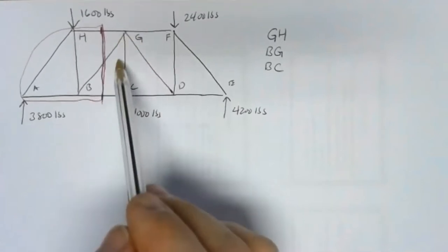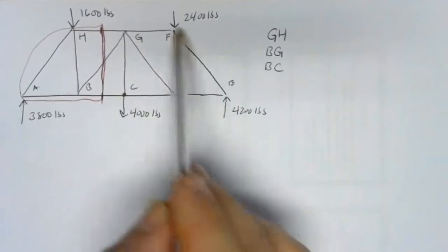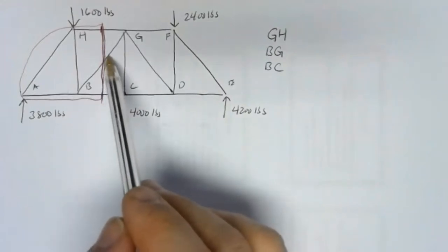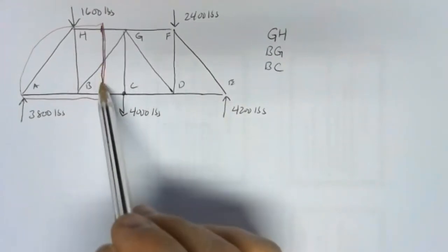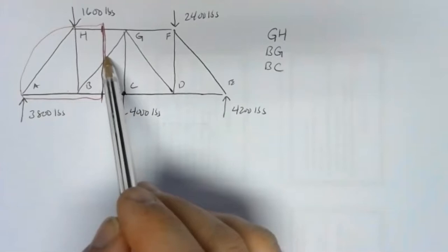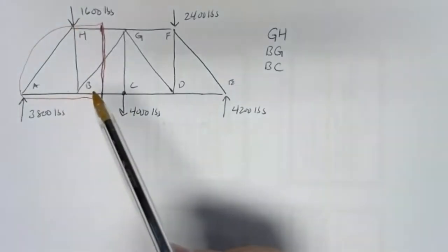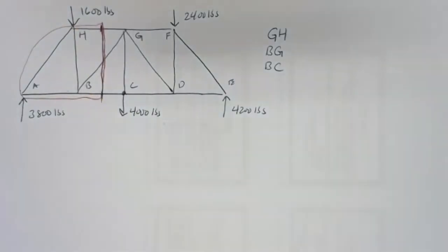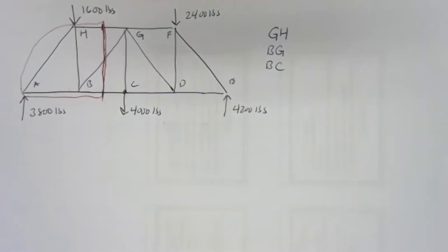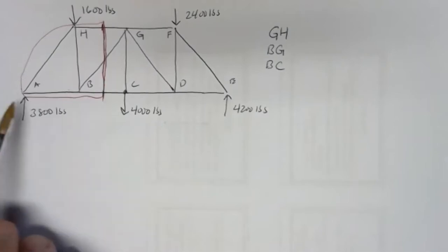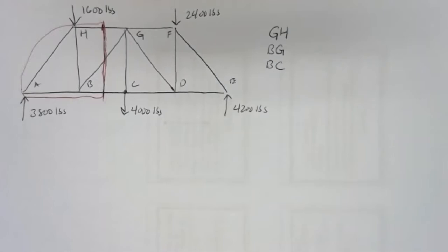So this part of the truss is exerting some force. The uncircled part of the truss, the right side, is exerting some force on the boundary here. There's some force on that member, and we're going to expose that force by cutting through it. Just like in working with free body diagrams, when we built our system boundary, we could eliminate whatever was outside, as long as we replaced it with the forces it supplied. That's what we did when we did our free body diagram with the external problem.